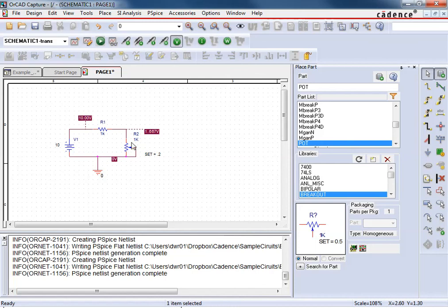Now again, you don't always have to have them tied together like this. In other cases, in some of the other labs we're going to be doing, we won't have these terminals tied together. We'll actually be using it as a potentiometer. Now when you wire this up in a circuit, technically, it doesn't matter which terminal you short together versus which one you don't, but it will determine whether you turn something clockwise and increase the resistance, or whether you turn it counterclockwise and increase the resistance. That is going to be determined by which leads you have shorted together.